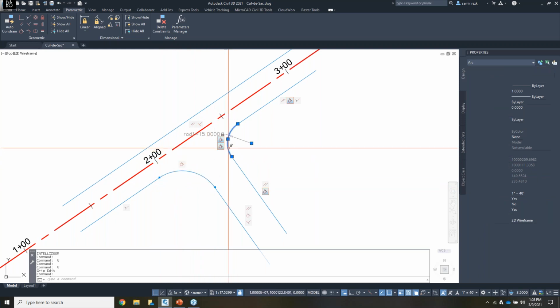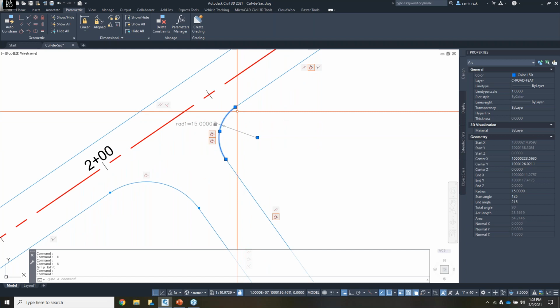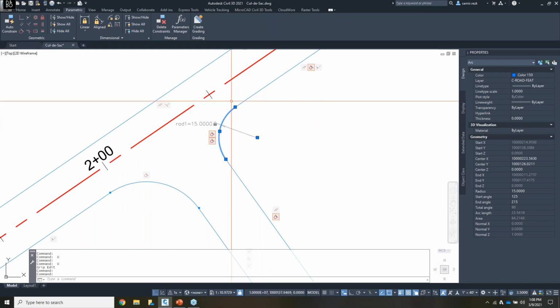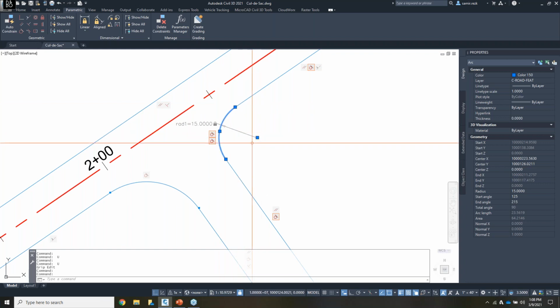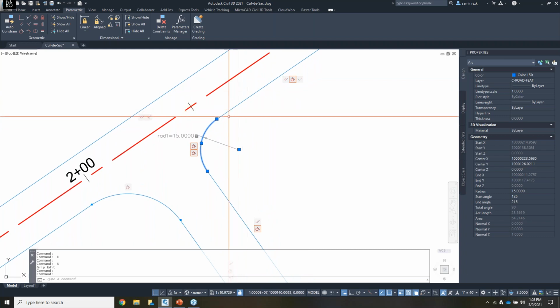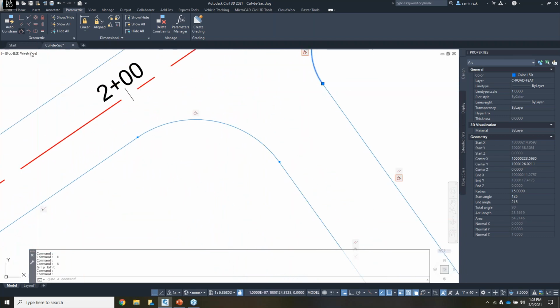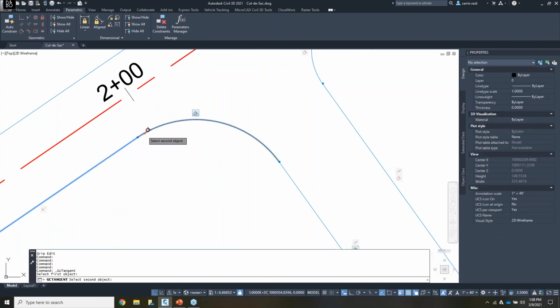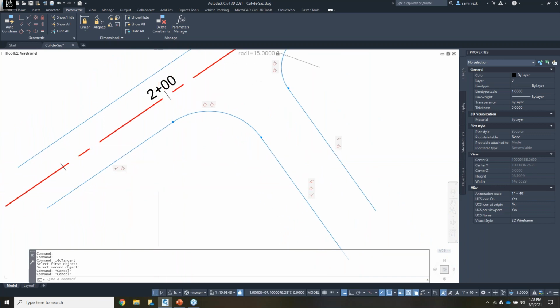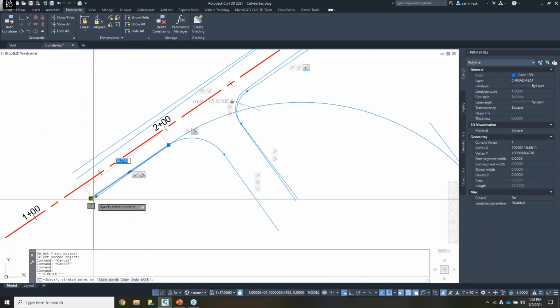For example, an arc has 4 points of freedom. There is an end point on each side, midpoint, and a center point. Each grip is a freedom point, and we can change all of that individually, or we can take away some of that freedom. So I can say, that endpoint needs to be tangent to another line. So I can apply a tangent constraint similar to this end. This line needs to be tangent to that line. Now I have removed a freedom from it, so it's going to always maintain tangency.